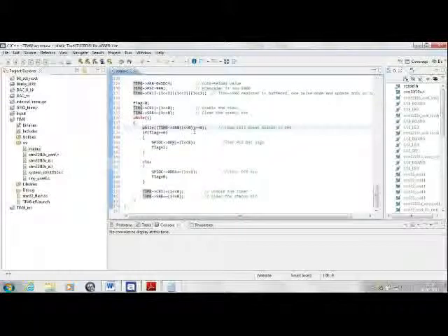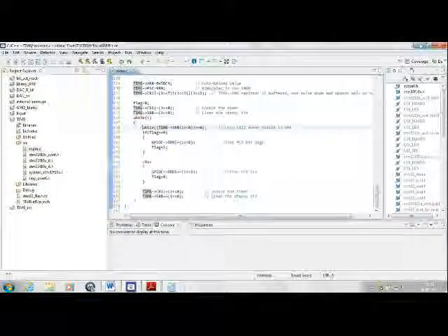It will directly fall through because the status bit won't be 0 here. That is why I reset this bit here and again wait in this while loop till 1 second passes by. This is how this code works. We'll now connect the kit and try and load this code and see how the LED blinks with 1 second on time and 1 second off time.